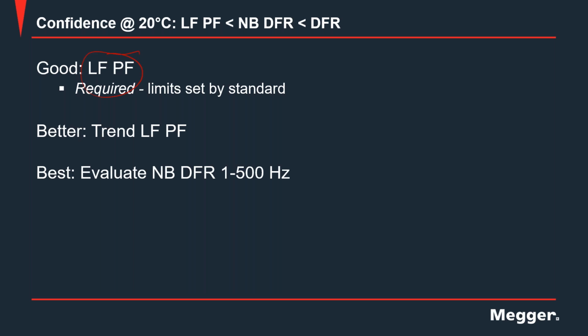The difficulty here is temperature. It's difficult to determine. And what we have seen is that the methods sometimes used to normalize to 20°C the power factor value tested at, say, 30°C, are not always correct, and that might be misleading.